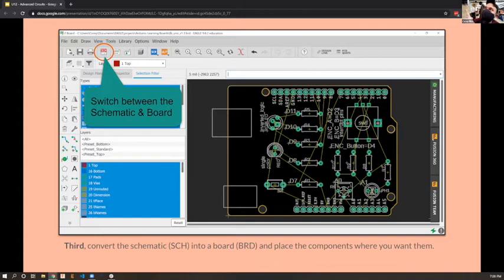Also, it's worth noting that over here, here's the Fusion 360 button. You can link this back and forth. The neat part about using Eagle and Fusion 360 is that in Fusion 360, if you say I have this much of an area for a board to fit in, you can say that area is going to be a board and then export that shape into Eagle. And then that's your board shape in Eagle that you have to play with.